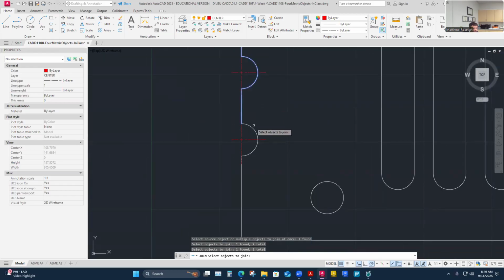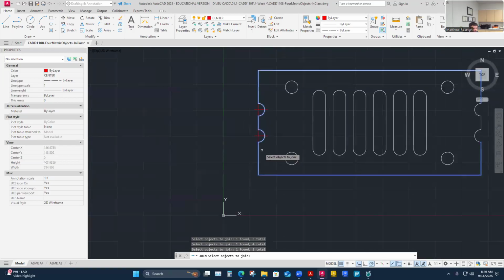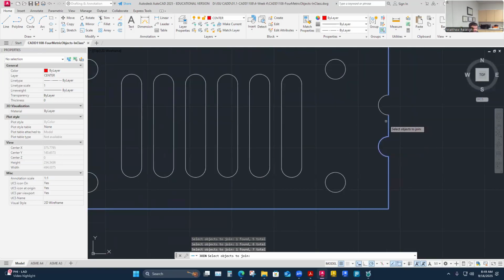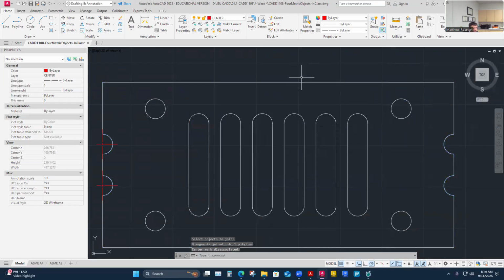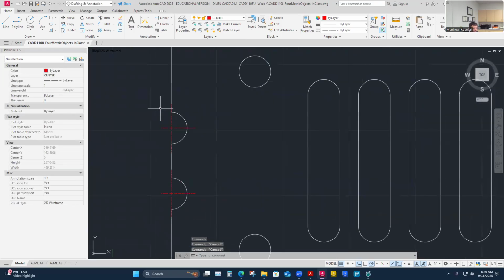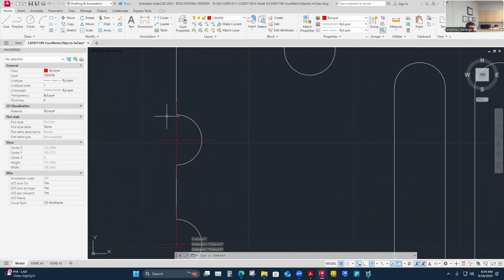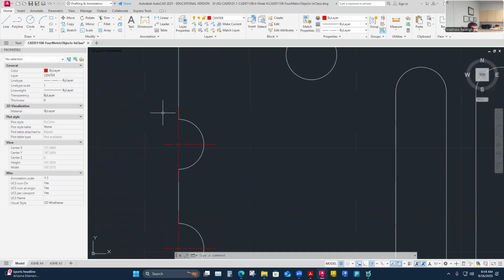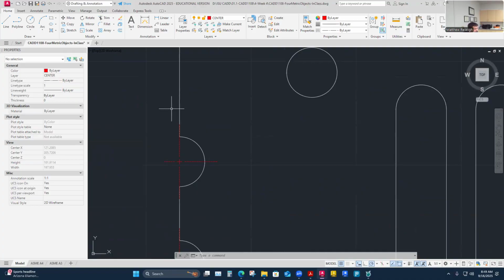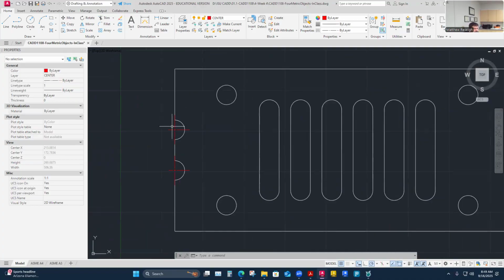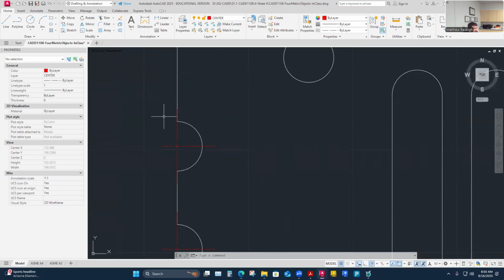And I want this line segment, and I'll show you why in just a second. I'm going to show you another command that I don't know if I've shown everyone. It's probably in my videos somewhere. I'm going to select all those. Now I've got a single selection here. What's going on here is just based on which line I placed on top of which line, right? So you get a center line over an object line here. I don't want that, and that'll show up that way on your drawing. Object visible lines are priority on all drawings to not be overlapped or behind; they should always be frontmost. Everything else is a lesser priority than visible object lines.